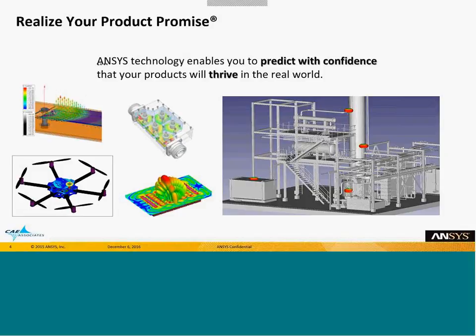So not only can we look at planar type of applications, board applications, we also look at waveguide type of applications, something that's very generic. Here it happens to be a 5-pole filter. I will be very careful because I know we have an expert in the room on filters. And we have a cavity filter here that also uses dielectric resonators as well. So the coaxial feed, and you will want to look at how the fields penetrate in that cavity. The penetration here depends on those openings between those cavities, and with the simulation tool, you can visualize it.